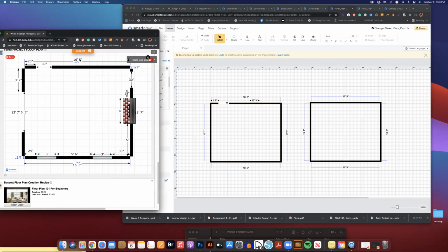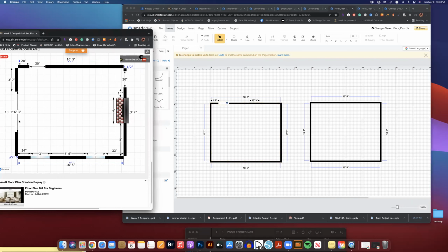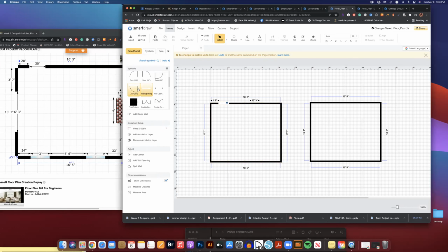The next thing I want to do is create this 6 foot 3-inch opening. So I will take another spacer out. It's going to rotate. I'm going to change it to be 6 feet 3 inches. I'm going to say okay. I need this to be positioned at 3 feet 7 inches. So I'll just change this to 7 inches. Say okay. So now our left wall is complete.